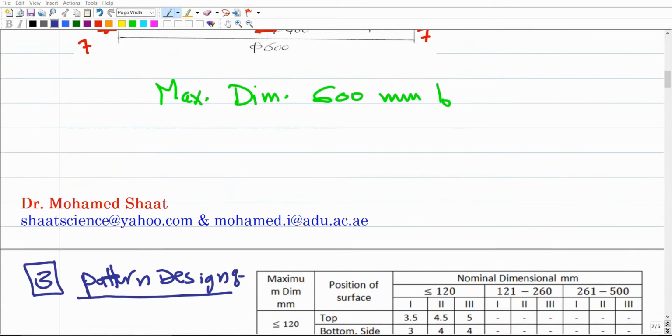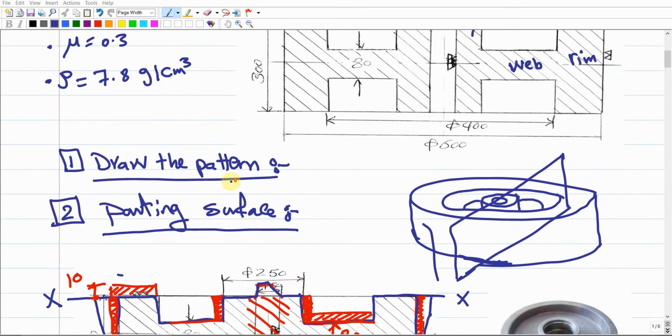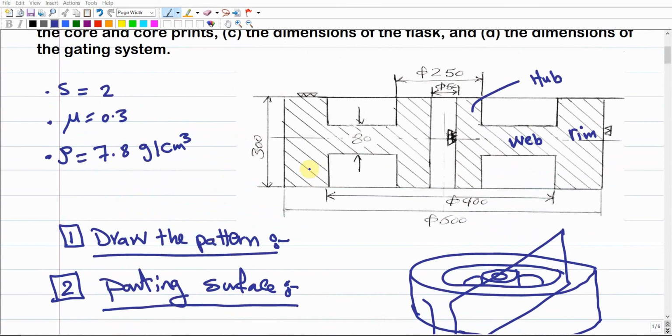If we go to the shape, the 600 in this given product connects two surfaces or two lines as given here. The 600 connects this line to this line. And as you can see, the surface has a machining allowance on this side, but there is no machining allowance here. So what does it mean? It means that I should add a machining allowance to this surface because I'm going to do machining for this one. From the first look, we would say that there is no machining on this surface. But actually, there is machining on the other surface as well.